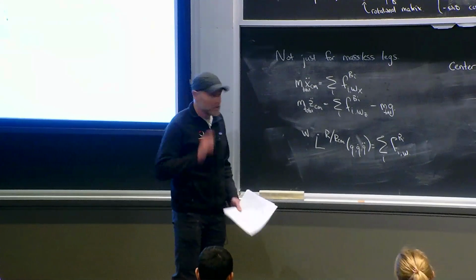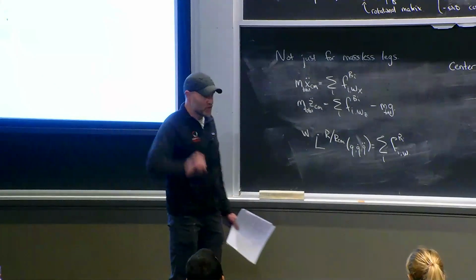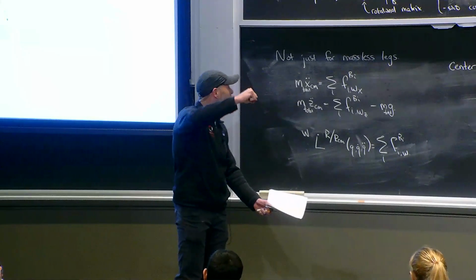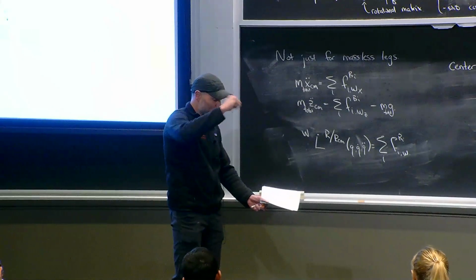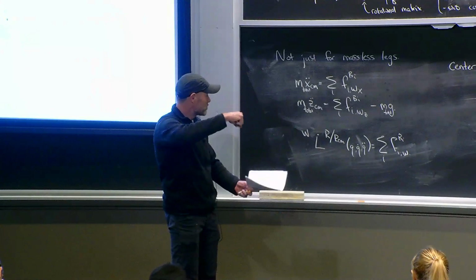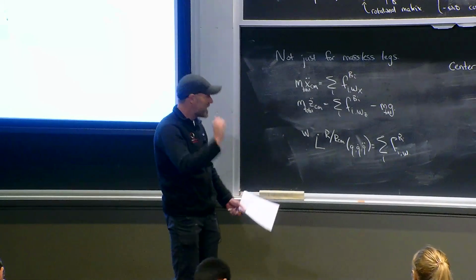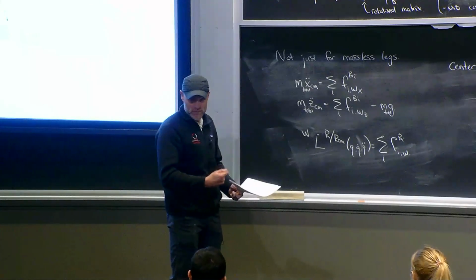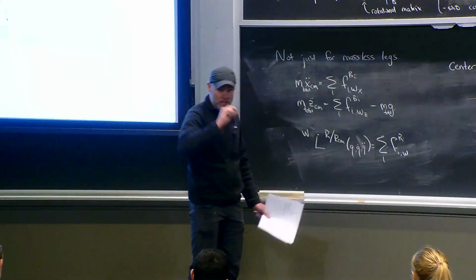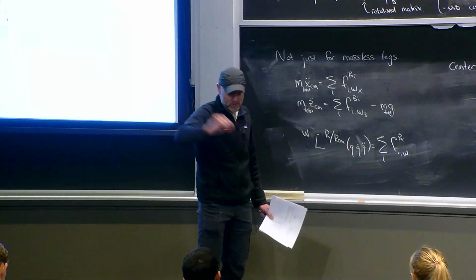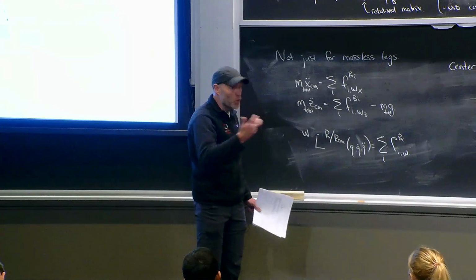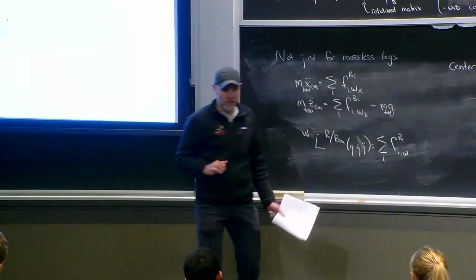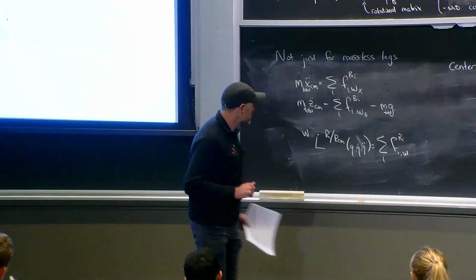Okay. I want to make sure of the high-level thread. Robots got easier because we could separate foot from center of mass dynamics, and we can keep that abstraction. And there's a natural analog of a single body moving through to the whole dynamics of the robot. It's just controlling the location of the center of mass and the total momentum around that center of mass. And you have to pick a frame for that. World frame is the common one.